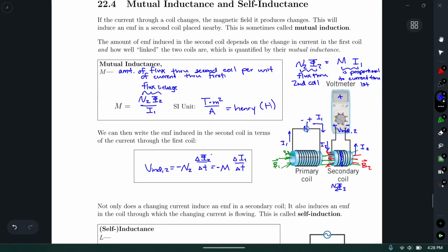So that is actually exactly how wireless charging works. You just saw an example of it for the light bulb, but that light bulb could be replaced by your phone if your phone had a coil in it. And many new ones do, as does the wireless charger. And so through mutual induction, you can have a current induced in your phone coil to charge it up without it being directly connected to the charger coil.